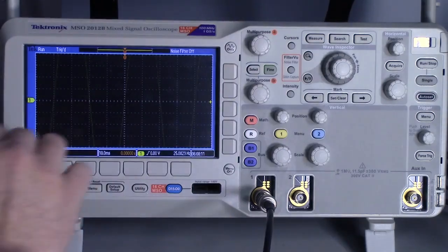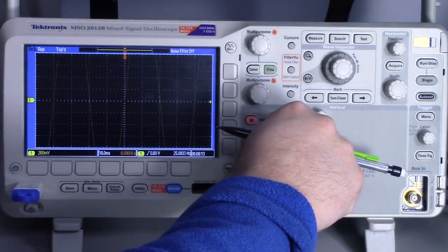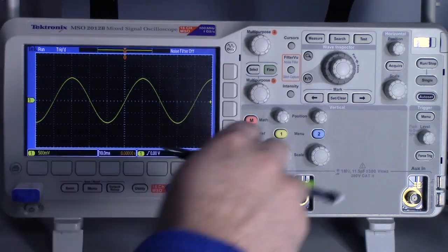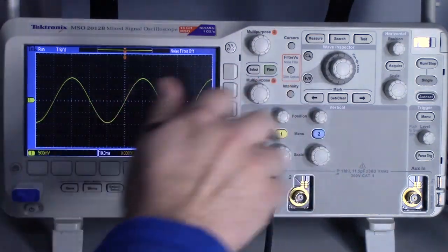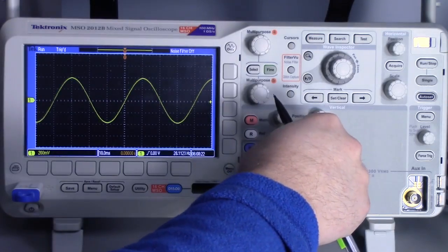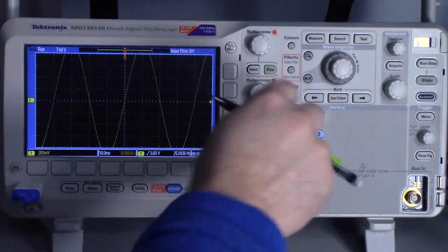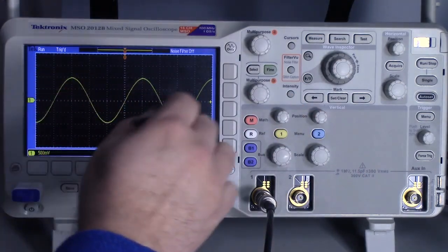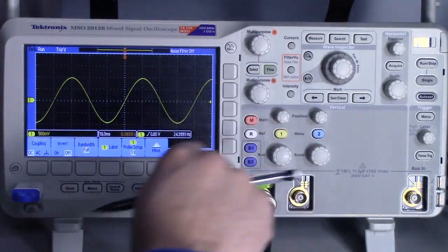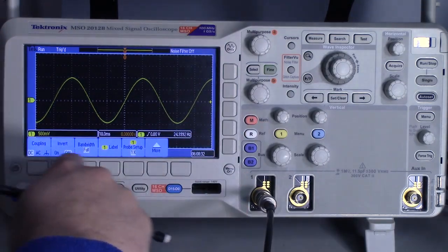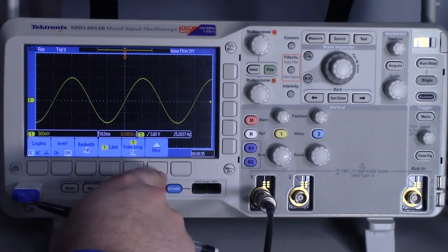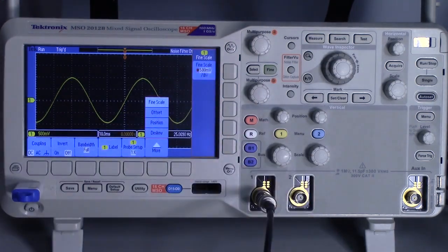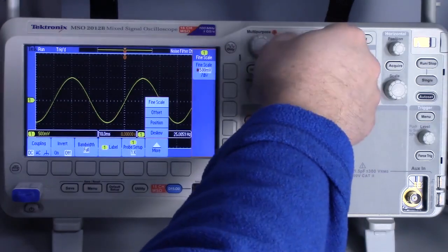So now it hasn't changed the size, but it has changed the scale. I'm now at 100 millivolts per division, and I want more. So there we go. One of the things about this knob is that its default is that it goes from like 200 millivolts to 500 millivolts. So if you want to see more of this wave, you can just press the number 1 to bring up this menu. These are the soft keys, and press this more button. And so now I can change the scale a little bit more finely.